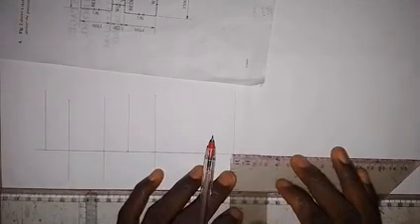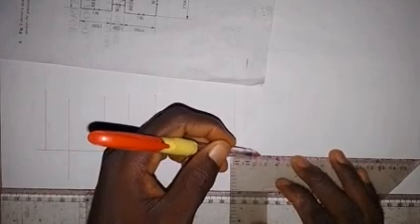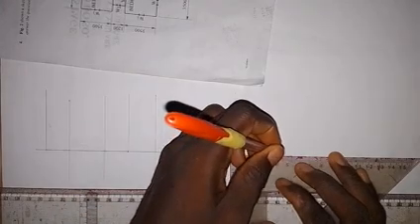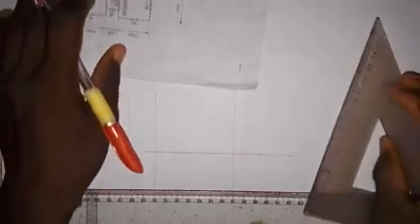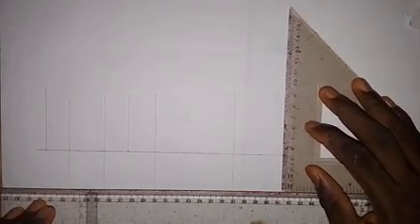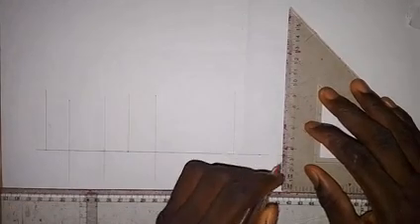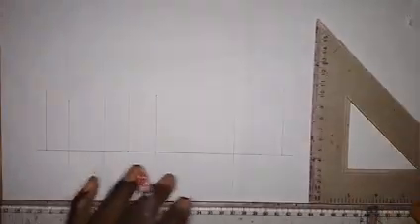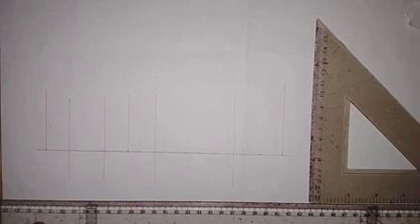So I have to take a measurement of 44 millimeters from here. I need to extend this line. So 44 millimeters, this is 44 millimeters at this point. At this point, we have to draw a vertical line, so we take it up. The cutting plane does not touch it, so we only see the edge of that wall. So these are the 4 walls that we are going to produce their foundation.